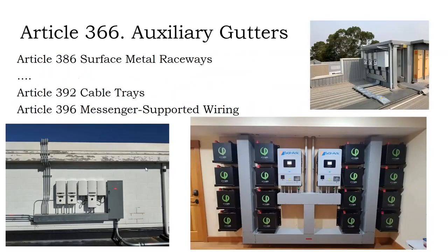Since we have this picture and we're not too far away from it, it's a little hard to see, but there are these little black connectors on that EMT. And on this indoor picture, you don't see any coloration, they're just metal connectors. That's the difference between an outdoor rated connector and an indoor rated connector. The outdoor rated connectors have a little bit more stuff on them.